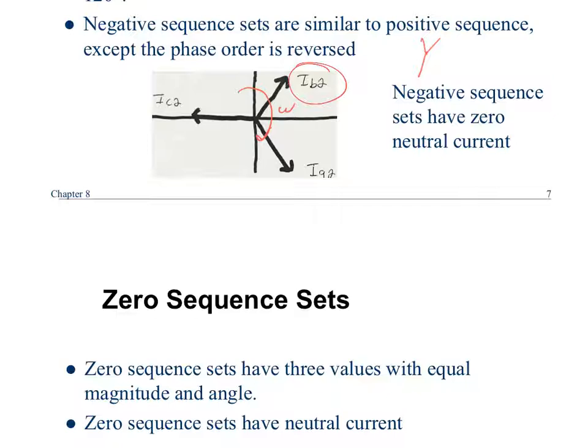But from a generator perspective, say a station has 3 generators cranking out megawatts. What if those are getting negative sequence elements? That would tell me there's a problem either with the generator or with the system. Most likely it's the generator, because the system has thousands and thousands of generators and loads, and it's going to be pretty closely balanced at that transmission level. Not perfect, but pretty close. So if you have excessive negative sequence elements in the currents from your generator, that probably tells you that you've got an issue with your generator.